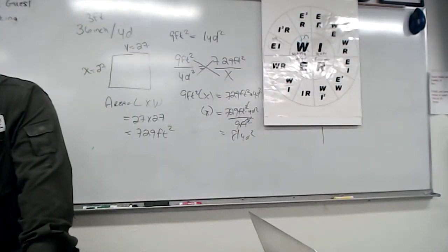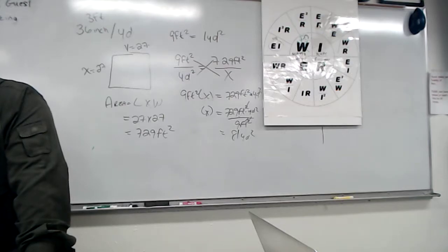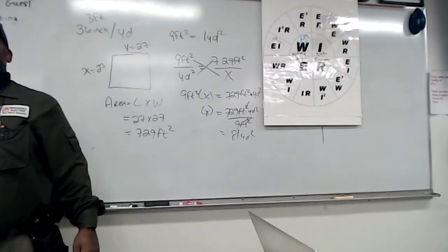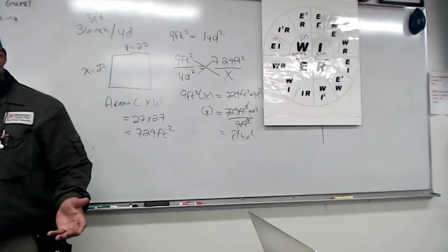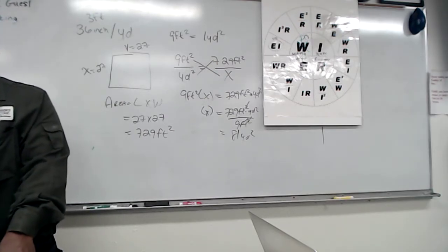So it's got to be one of these device boxes, and it says 1.5 inches. And there's not just one box that's 1.5 inches on the device box. Well, they got 2. We got 2 of them. Would you agree that it's probably not a 4 inch nowhere on this box? So it can't be 4 inch. It can't be a 4 by 2.5, 2.8 by 1.5 inches because it's not a 4 square box. It's got to be a single measurement.